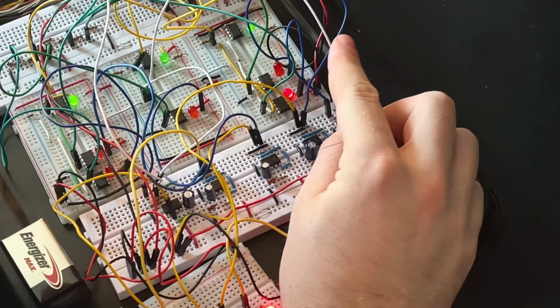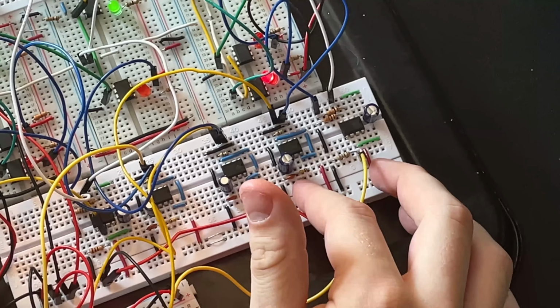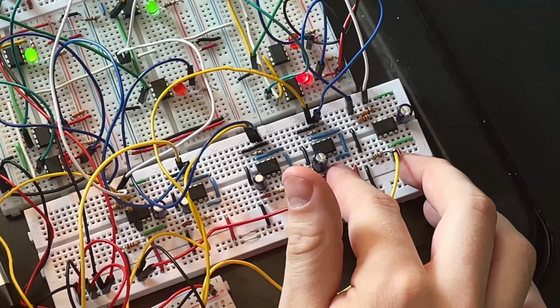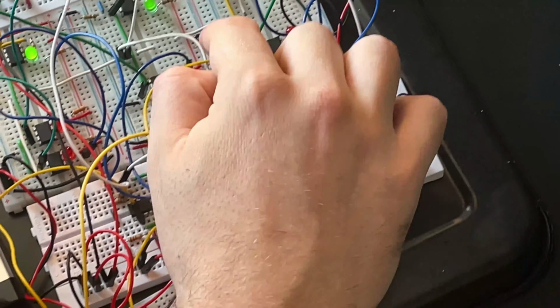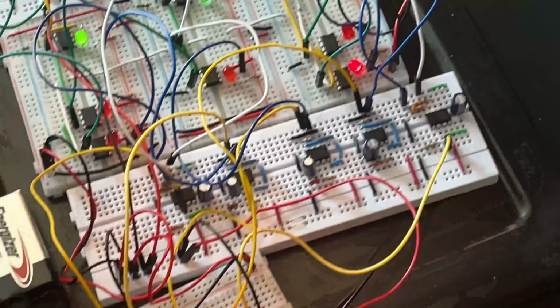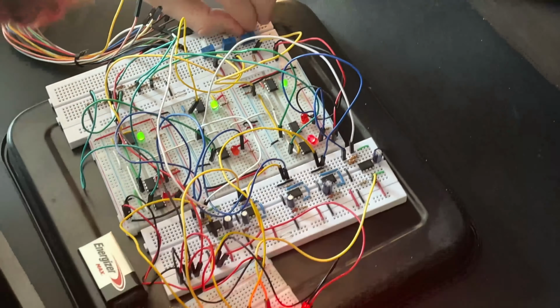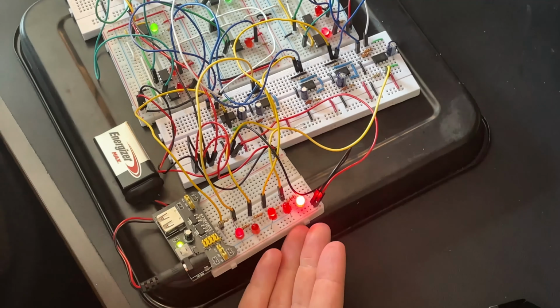The second blue wire takes us to the first of 3 monostable multivibrators. What these let us do is get a short pulse from the comparator, and then use that to keep the output on for a longer amount of time. So we take the output of this yellow wire. This one, if we follow it, is heading to this second LED. We can turn it on by twisting the knob for just a second and then back up, and it stays on even though the knob is above a safe threshold, and then it turns off.